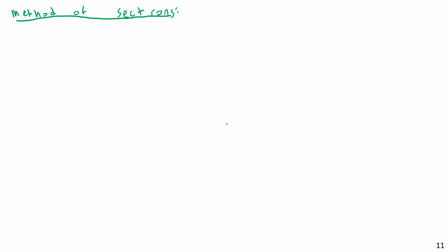If you have 3 or fewer, you can solve for those reaction forces using simple rigid body equilibrium applied to the entire truss. Now, this cannot always be done, especially if you have a pin-pin truss or a truss with multiple pins on it. But that's why I will say, if possible,